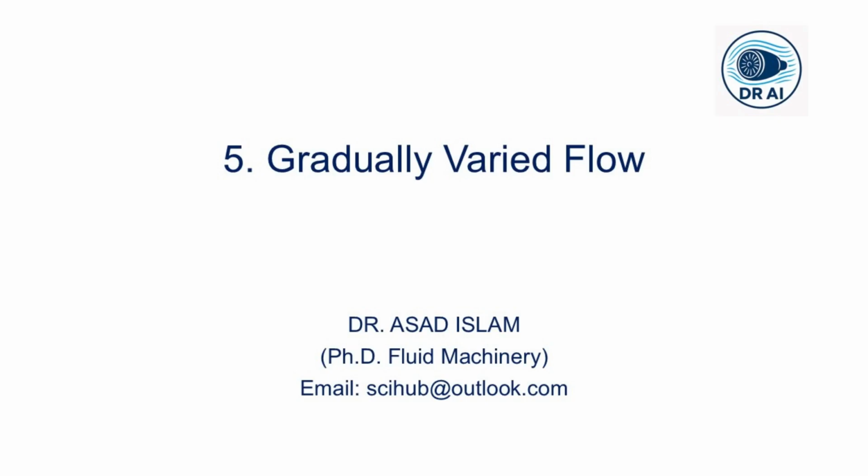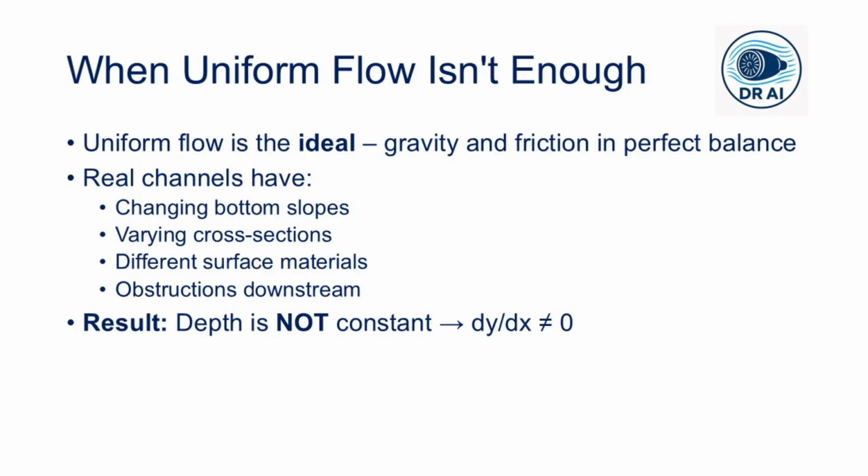Over the last few sessions, we have been building our toolkit. We started with the very fundamental characteristics of open channel flows and the Froude number. We then derived the speed of surface waves, which gave physical meaning to that Froude number. We then explored the powerful concept of specific energy and how it governs the flow transitions over bumps and through contractions. And finally, we mastered the Manning equation for uniform flow. So that was a perfect, idealized state where gravity and friction were in perfect balance and the depth remained constant.